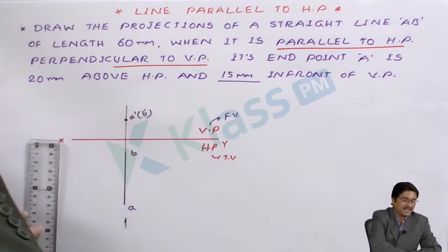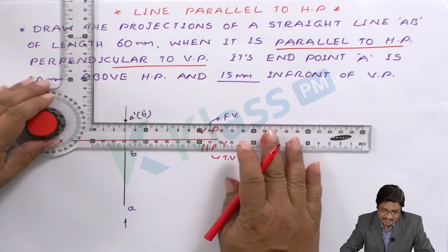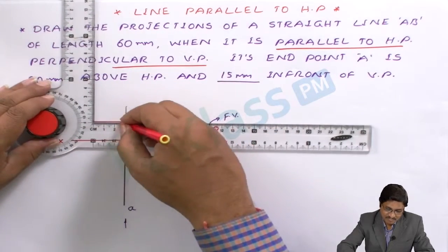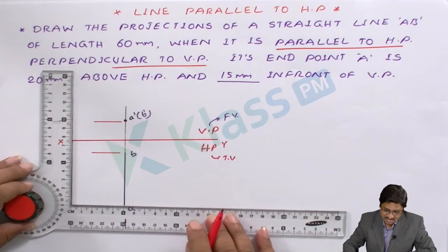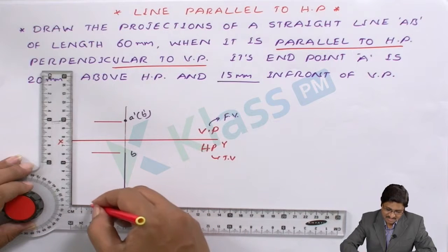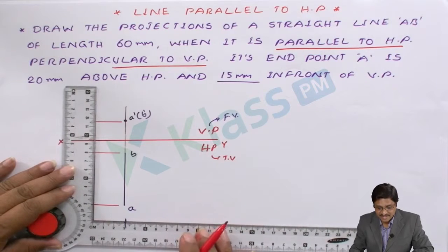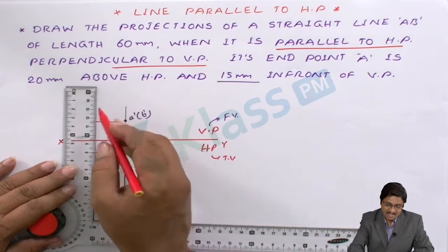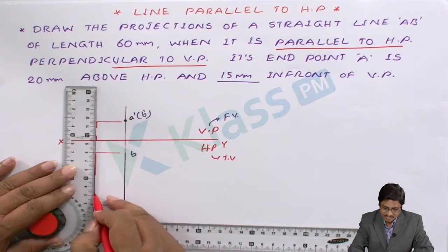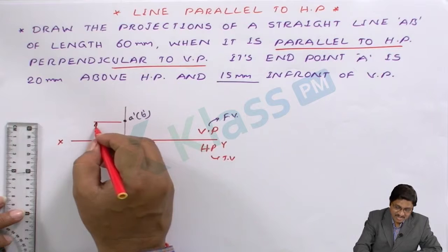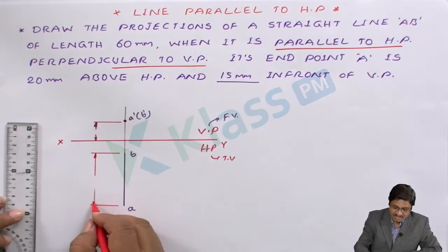Once you have completed that, you have to identify the dimension lines. The dimension lines are to be drawn. All the extension lines must be drawn for the same length, leaving a minimum margin so that you can differentiate which is the dimension line and which is the object line. For that, you must proceed like this. Then the arrowheads are to be drawn very systematically, with more length to the arrowhead, and then write the dimension.